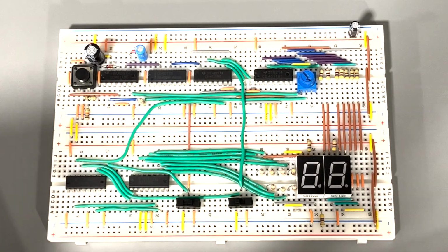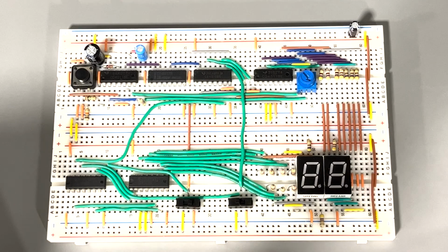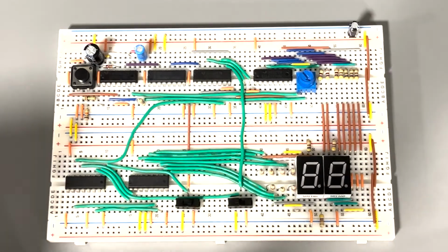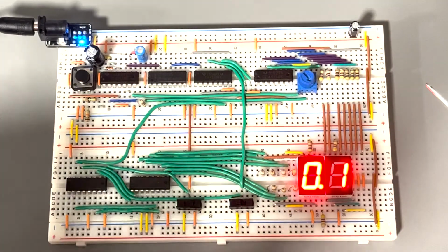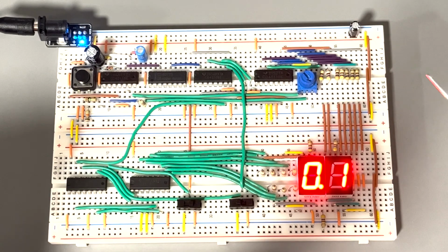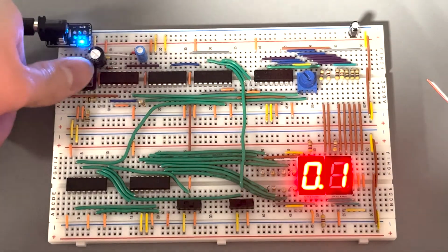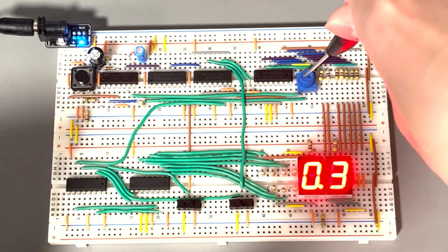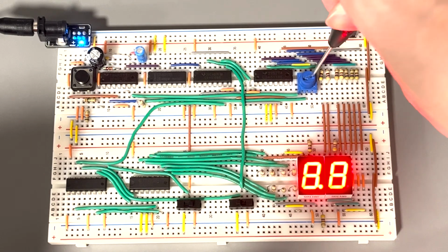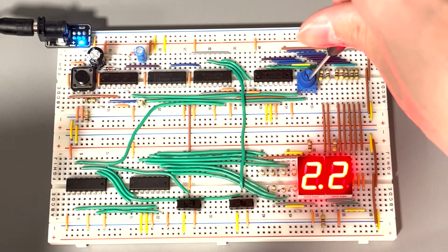The preset, carry in, up, down, and reset pins need to be conditioned for this chip to work. The up-down pin determines whether the circuit will be counting up or down. For this circuit, I connected a potentiometer to the RC2 part of the NAND gate oscillator. And what it does is, when you decrease the resistance, it starts to count faster. And when you increase the resistance, it starts to count slower.